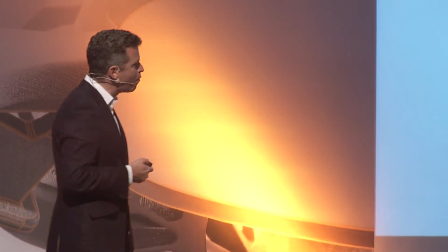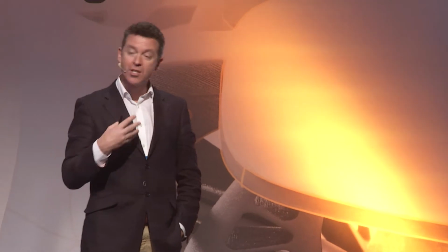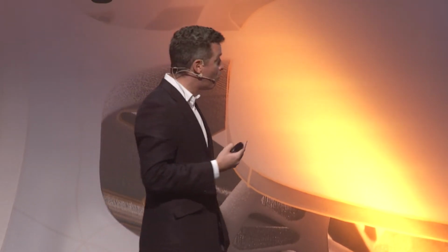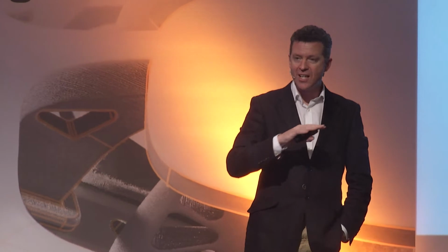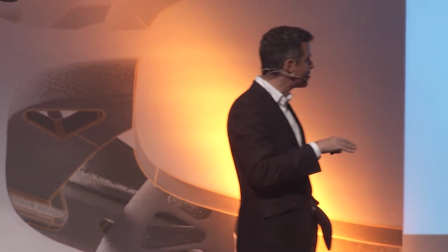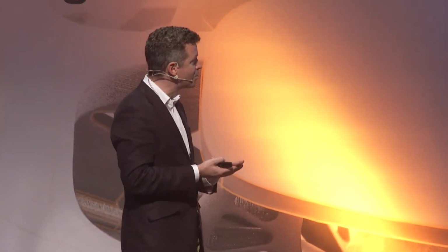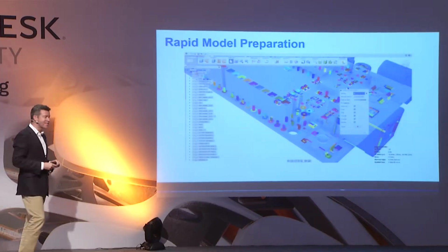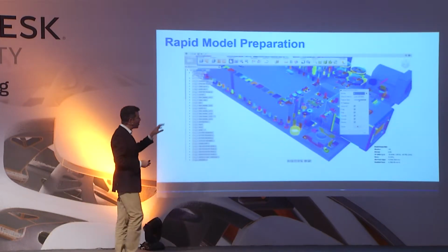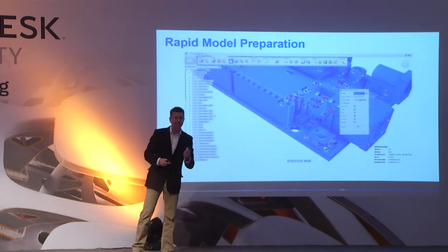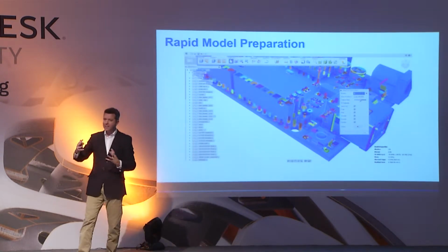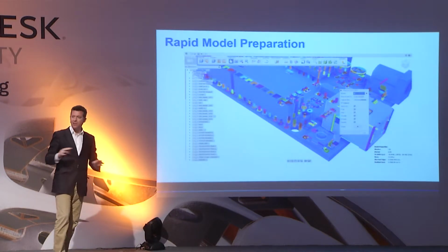So through the use of a product called Sim Studio Tools, which comes with our simulation software, or through Fusion, it's possible for the engineer to simplify all of these details. They can effectively select the entire model and specify fillets, rounds, small details, small protrusions or extrusions in the geometry below a certain size and eliminate all this detail. If these components are not adding anything significant in terms of heat, or they're not containing the airflow, they can go. They're not required.